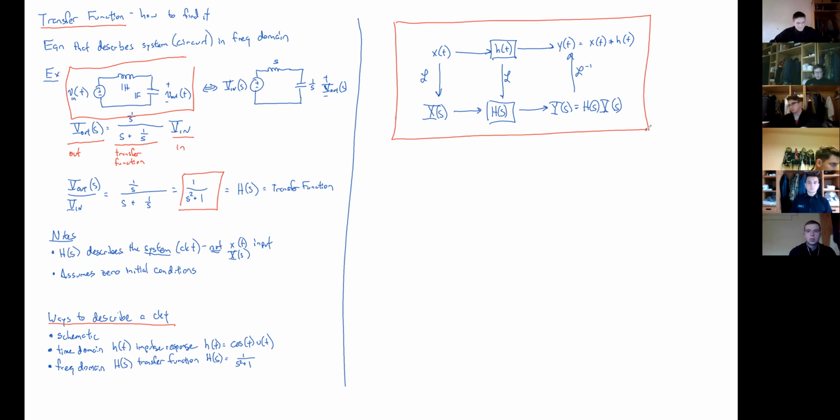Sir, isn't that just a very graphical, or with arrows, way of saying, instead of doing it with the integral, doing it with Laplace transforms, like how we did 4 classes ago, right? Yeah, so you've seen this before, the exact same thing. But the part that you didn't know 4 classes ago is how to derive this part, which now you know: impulse in gives you h(t).